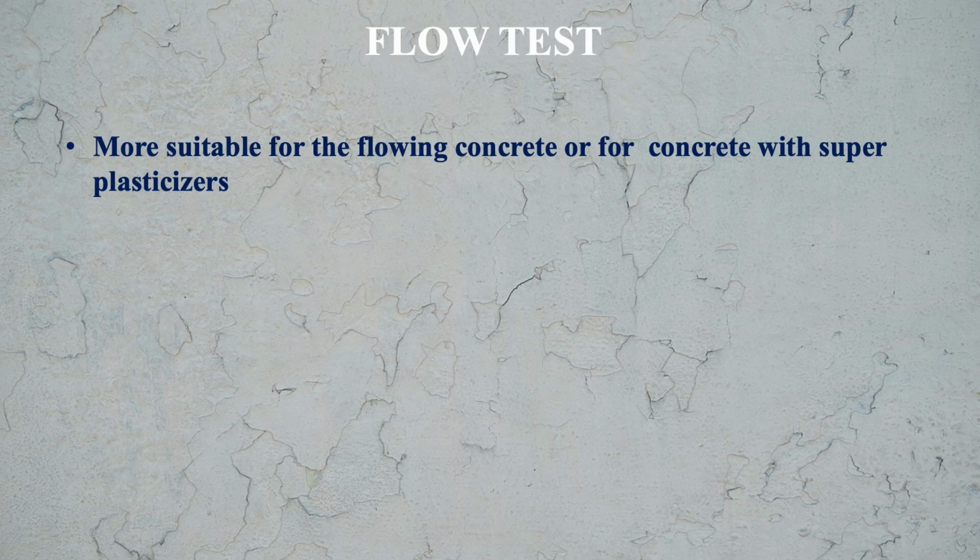Flow test is more suitable for flowing concrete or concrete with superplasticizers. It means concrete which has a high water quantity or has superplasticizers, because the use of superplasticizers in concrete makes it more workable. It can easily flow. For such concrete, we will use the flow test for measurement of its workability.